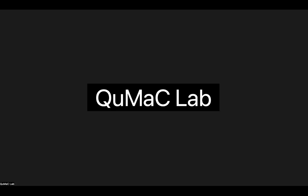So this is not the generic case, because you can have a situation like sine A cos B plus cos A sine B. That will give you sine of A plus B. If you had a minus sign, it will give you sine of A minus B, but not the other one. So you can use symmetry. The reason for this is that the previous mixer had 90-degree phase shifted terms going into the two LOs. So by combining it with an IF which is also 90-degree phase shifted, you can cancel one of the terms and leave one of the terms.